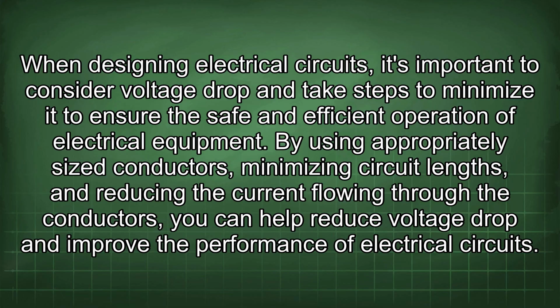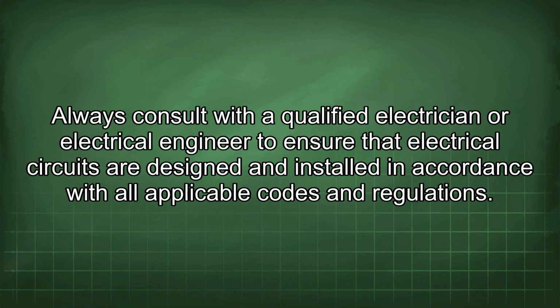By using appropriately sized conductors, minimizing circuit lengths, and reducing the current flowing through the conductors, you can help reduce voltage drop and improve the performance of electrical circuits. Always consult with a qualified electrician or electrical engineer to ensure that electrical circuits are designed and installed in accordance with all applicable codes and regulations.